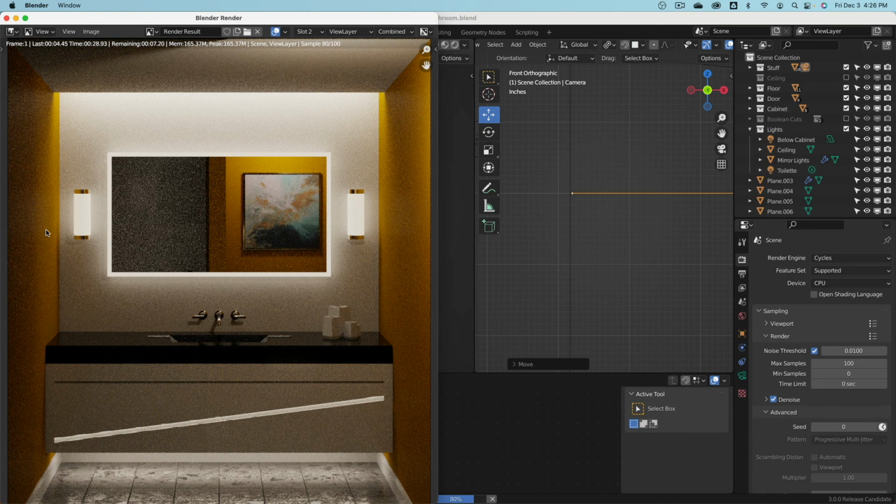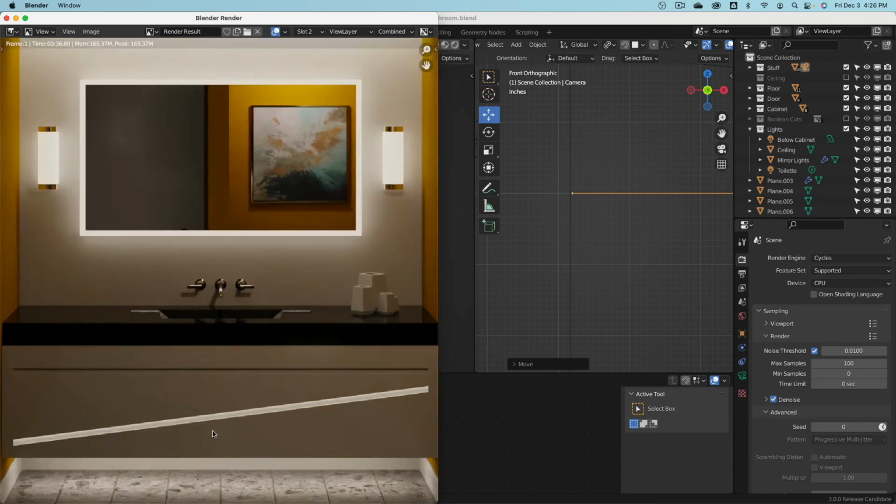While this renders, by the way, we can give the room a bevel command too. Very tiny, because we don't have these razor sharp edges. They're slightly rounded. Yeah, there we are. Now we can change the color for the chrome. That feels a little bit too dark. We can give this a white porcelain.